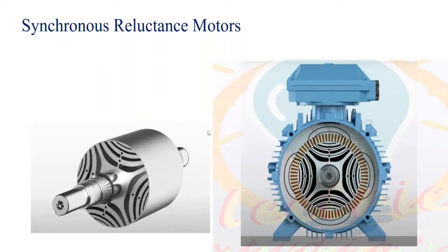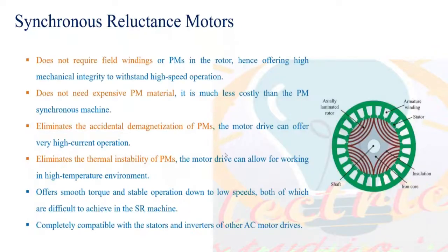They don't want to completely come out of it. At the same time, they are keeping their induction motor where they started their journey. It is still there with them. At the same time, they are adding additional motor technologies wherever required, like Toyota. Toyota uses multiple motors and one engine. Similarly, Tesla uses a combination of multiple motors, so they run the different motors at their different higher efficiency regions.